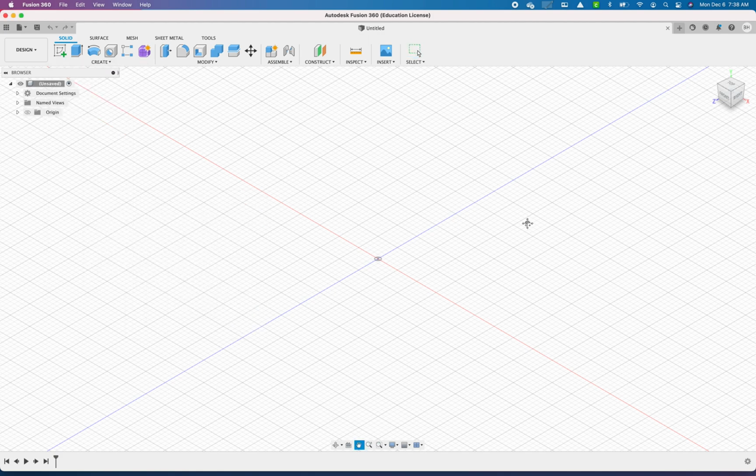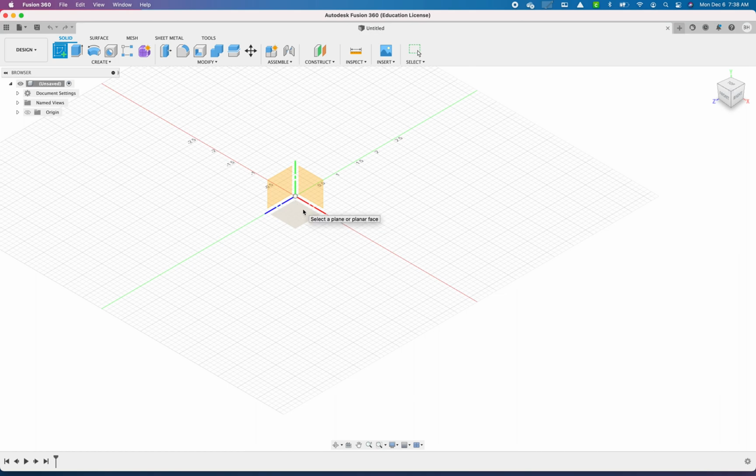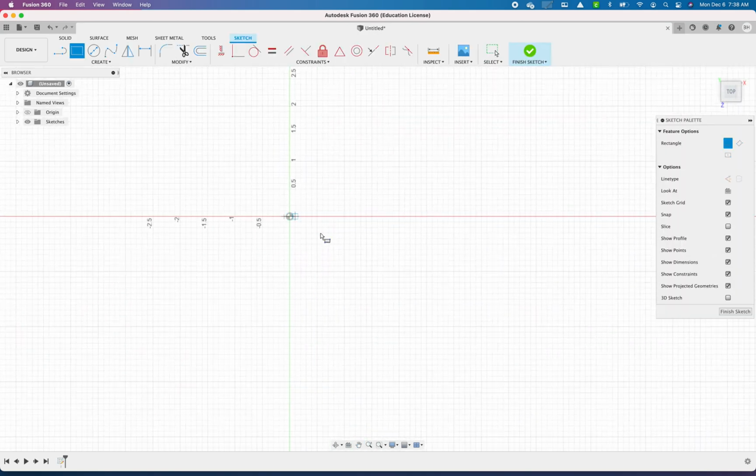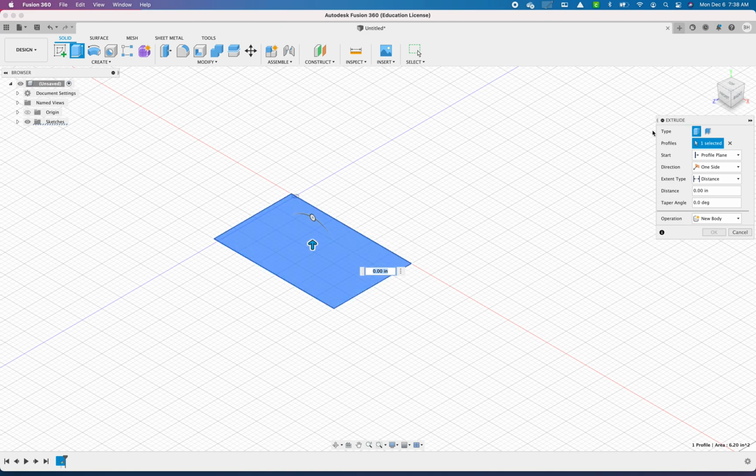Okay, so we're going to start from a sketch here and start from Extrude. Obviously, that's the most simple one. You're working from a profile of any shape, and you're using Extrude to pull that shape out in 3 dimensions. That's a linear extrusion or a linear motion that creates a 3-dimensional object.